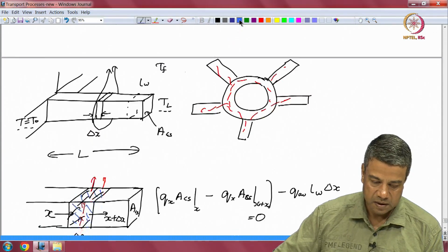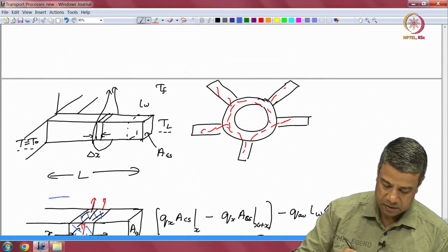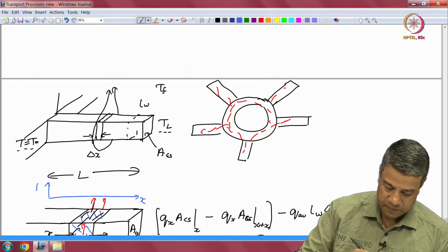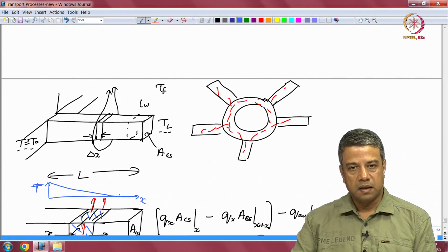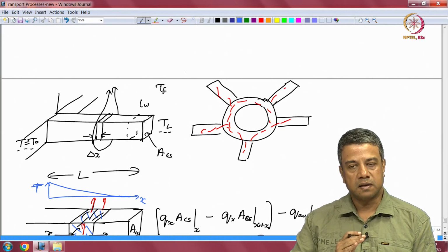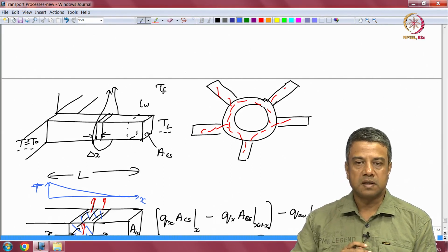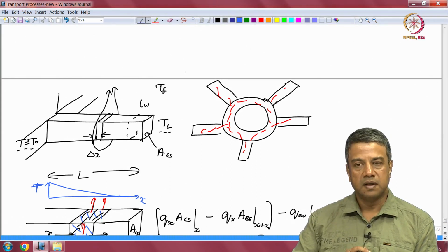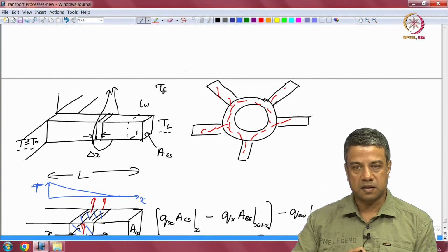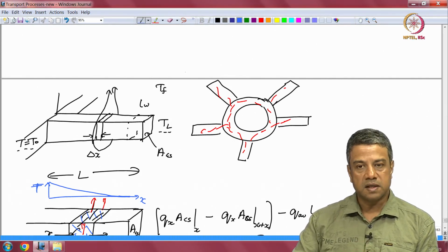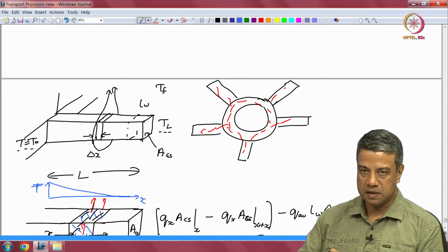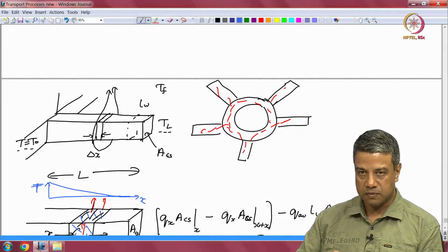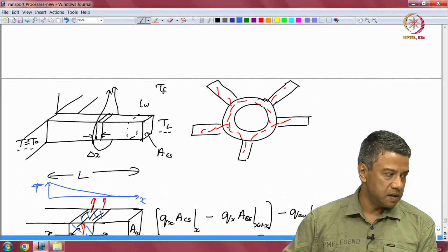If I plot the temperature as a function of distance along the length of the fin, the temperature decreases from one side to the other. So, this is not actually a constant temperature, which is assumed when the correlation is derived. For elongated objects, you assume that the temperature is a constant when you derive the correlation. In this case, the temperature is not a constant. However, we can consider it a constant if the characteristic length for the decrease in temperature is much smaller than the diffusion length, which is Gr to the power minus 1/4 times the equivalent diameter.